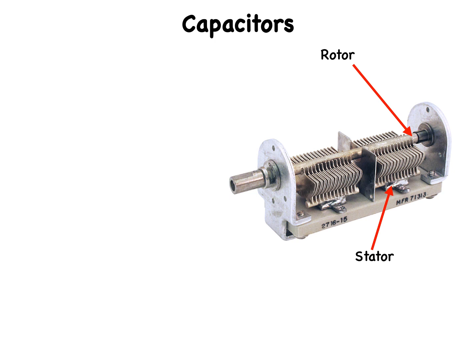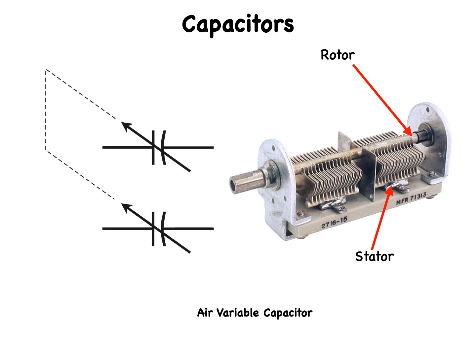All variable capacitors are non-polarized components, meaning that the external DC voltage you connect to them can go either way and it doesn't make any difference. Sometimes, 2 separate variable capacitors are connected together or ganged, as in this case shown here. In a ganged arrangement, 2 or more units are used to control 2 or more electronic circuits, but both components are varied simultaneously by tying the rotors of the 2 units together. This shows the schematic symbol for 2 variable capacitors ganged together.